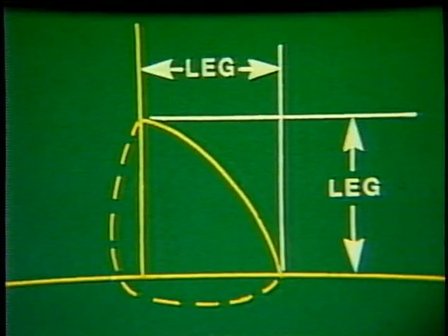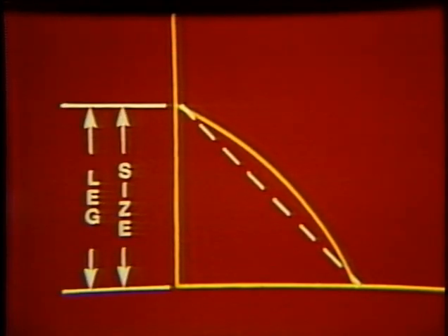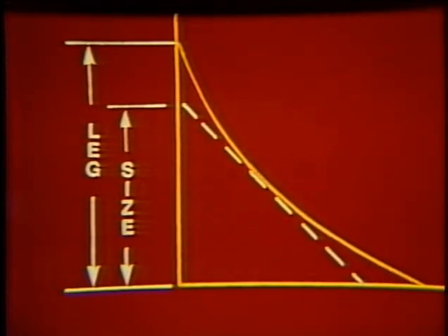The size of a fillet weld is often designated as its shortest leg length, a measurable dimension used to deposit the weld. The leg is the distance from the root of the joint to the toe. For strength, the size of a fillet weld is the leg length of the largest isosceles right triangle that can be inscribed within the weld. For flat and convex welds, the leg size is equal to the effective size for strength. However, for concave welds, the effective size for strength is less than the actual leg length.